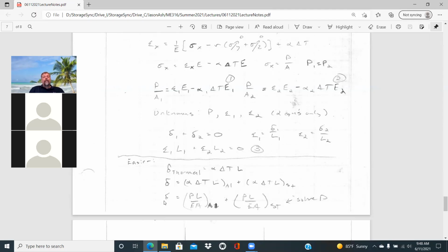And then based on that, we have the mechanical displacement. That would have to be the same combined. So looking at that compressive force, PL over EA for the aluminum plus PL over EA for the steel would have to equal that same displacement. We have the Young's modulus value of each, A and L. We know that the loads are the same within each one. So this delta, we can solve the value here, and we then have one equation and one unknown. We're solving for P in the second one.